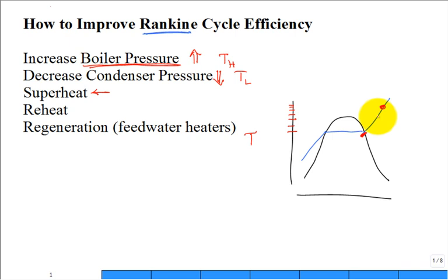Also, when you expand it through the turbine, if you expanded it, maybe you went down to this low pressure, well, you have a pretty low quality. I mean, it may still be 60%, but that means by mass, 40% are in liquid water droplets, which act like little bullets. They don't turn as easily as the vapor inside your turbine. So they smack in the surfaces where the vapor would turn.